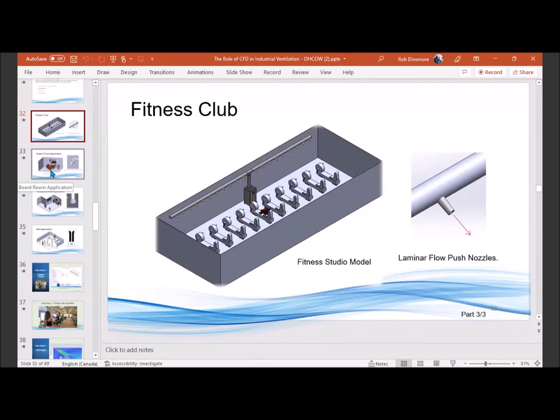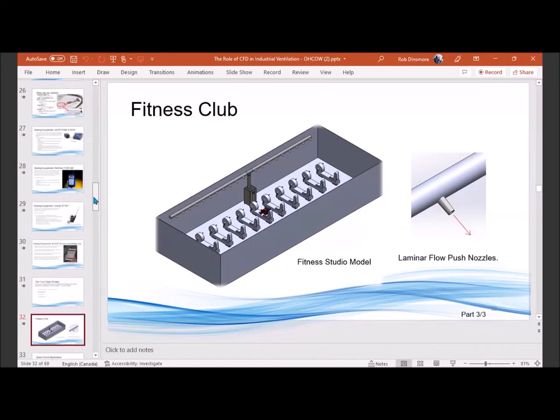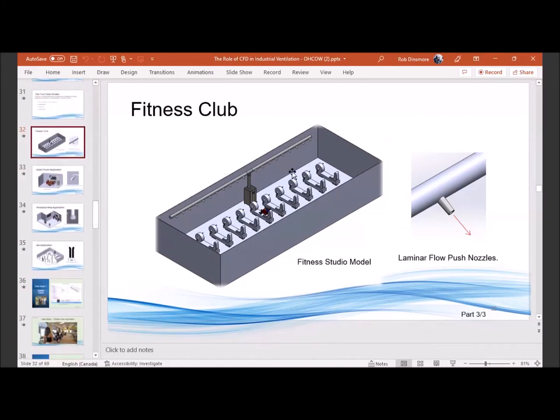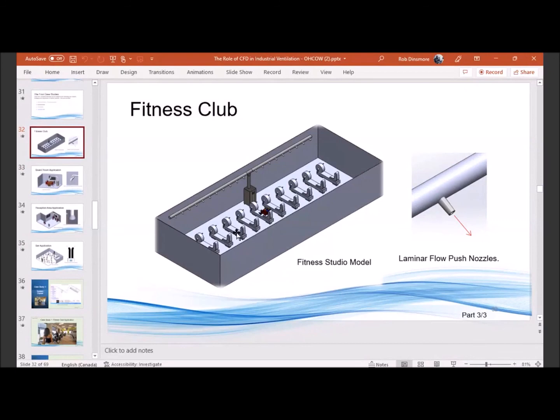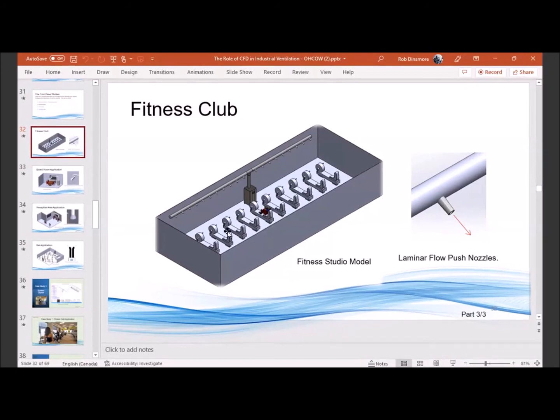It's a great question. Thank you very much. So our goal with these is always to go for a clean to less clean airflow pattern. We're always trying to get the clean air into the operator or the worker's breathing zone, and then have it come to the floor at floor level and be picked up, filtered, preferably mixed with outside air, and reintroduced. In this case, you're right, that will push some of the hazards to other people. Sorry, I speak in a world of industrial ventilation more than commercial ventilation, but it will do that.